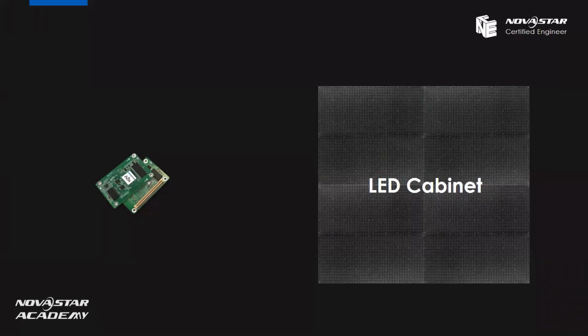Normally there is only one receiving card in each cabinet, because without a receiving card, the LED cabinet cannot show any image. But with the development of this industry, the pixel pitch becomes smaller, so the resolution of the LED cabinet becomes bigger. In this case, one receiving card is not enough, so our LED cabinet may have two receiving cards inside.